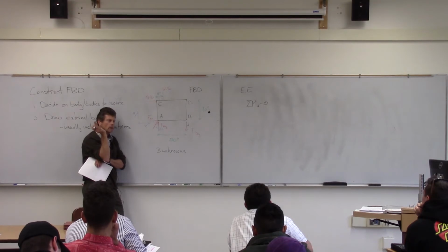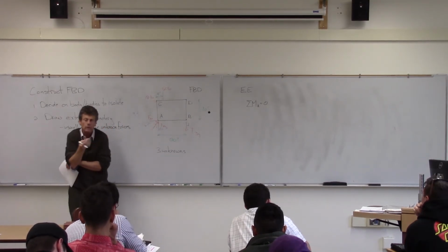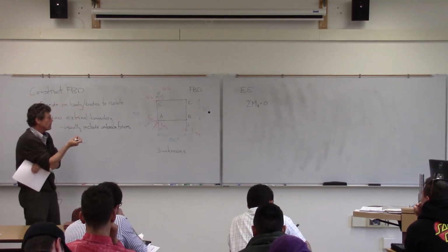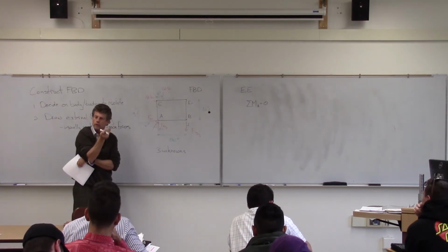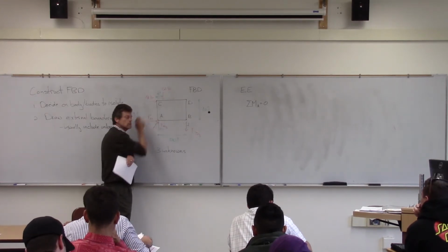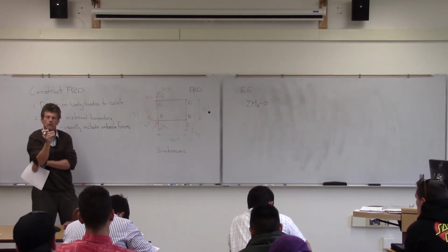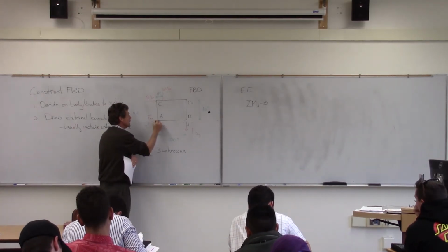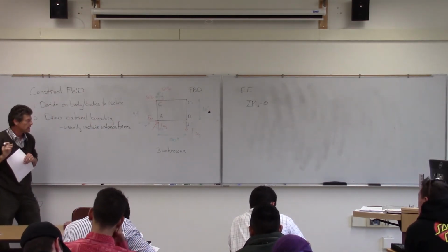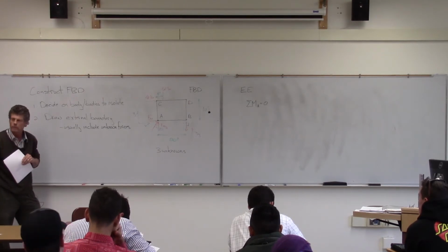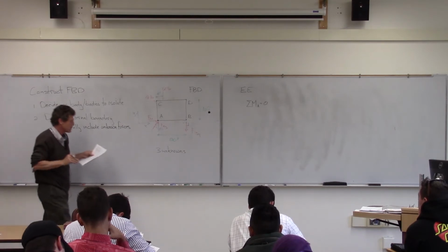0. There's no moment arm, right? So one of the nice things, our workhorse when we get into rigid bodies is going to be this moment equation. And we're going to find that it's nice. We can take this moment equation. What we want to do is move it to a point where we can get dimensions, and also a point where we can eliminate some unknowns. So if I can move it to this point A here, I've eliminated F of A completely. It's component x, it's component y. It can't contribute because the moment arm, it goes through that point. There's no moment arm for that force.